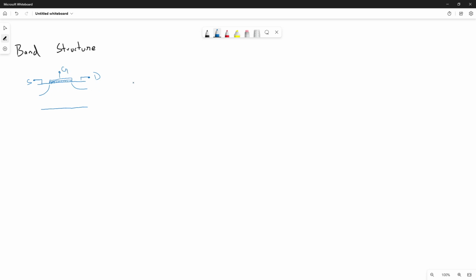Now what I'm asking is, in how many directions does the material profile vary? If I'm moving from left to right of this device, I start from this P. Since this whole device is P, these regions will be extremely n doped to bring them back to n level, so that will be n plus and n plus, but I'm just writing it as an indicator. As I'm moving from left to right, of course, I'm moving from an n-type region to a p-type region to an n-type region. Is there any other direction in which I can move to encounter a variation of materials?